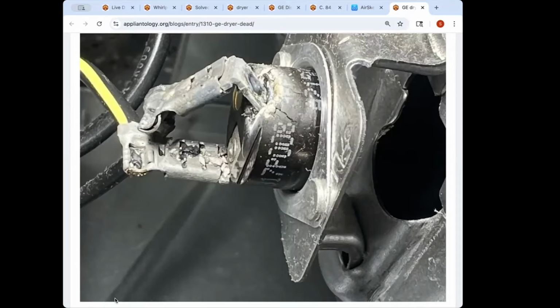Could be. And in this case, it was the high limit and not the safety or one of the other bimetals that went out. And you'd think if it was a combination of heat and amps that one of those would have gone too. True. And we can't discount manufacturer errors.